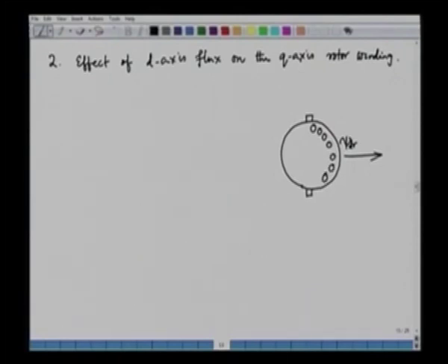So these are the conductors, and we are seeing the cross section of the conductors across the periphery of the armature, and the rotor is rotating in the clockwise direction as per the convention. So the rotation is omega r, the speed of the rotor. Now again we can apply the Fleming's right hand principle.